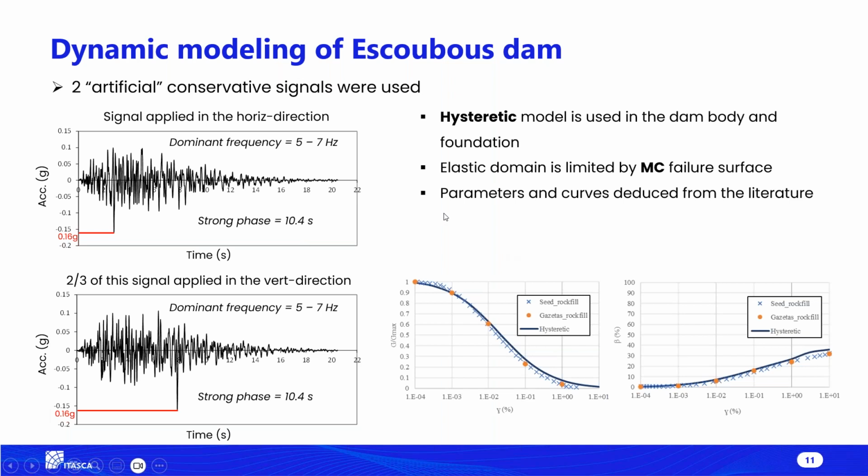For the constitutive model and parameters that we used in our dynamic simulation, for the dam body we used a hysteretic model, in the dam body and in the foundation. In addition, it was coupled with Mohr-Coulomb to limit the elastic domain by a failure surface. Most of the parameters and curves were deduced from the literature.